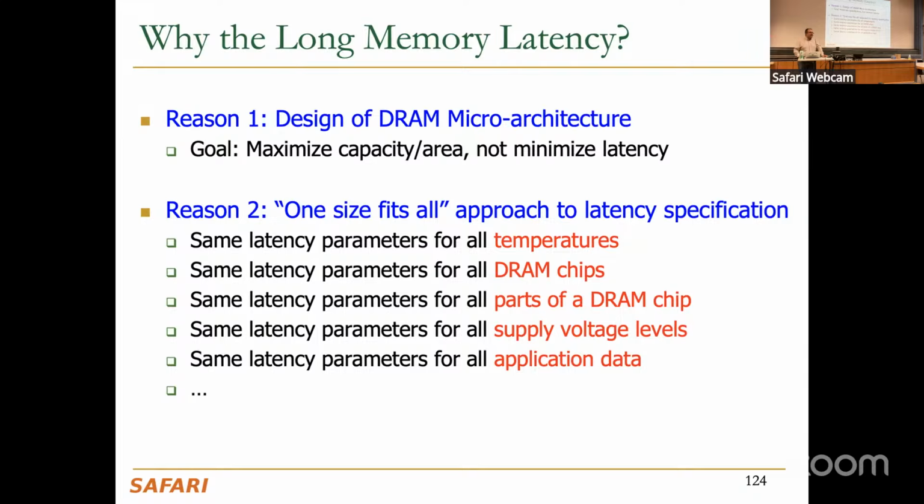So people also have that intuition that DRAM latency is dictated by the manufacturers and the memory controller is obeying those latencies. We can potentially go much faster, and nothing will happen. But if you don't do it carefully and you don't have a good methodology, then you might run into issues like low reliability, which you should be able to handle. So a lot of the ideas that I will discuss in reason 2 are going to be around that kind of methodologies.